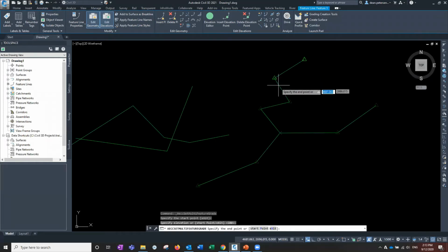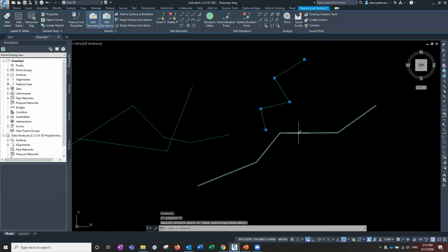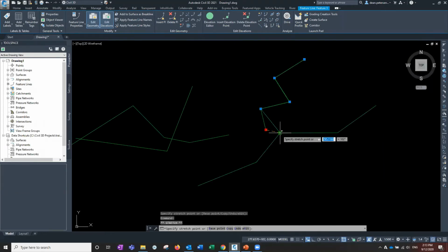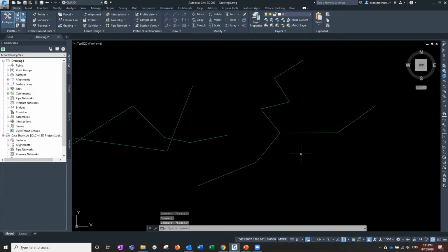And what you actually do, you need to trace. You can't just go to the end. You've got to actually trace down through the vertexes that it's going to trace this command to. Looks like you actually do have to snap them, so that there's an elevation difference there. That's a new one for me. So if I unsnap that and snap it onto there, then it should trace if it's at the same elevation. So let's check my elevation. It should be at 0, which it is. And so run the command.